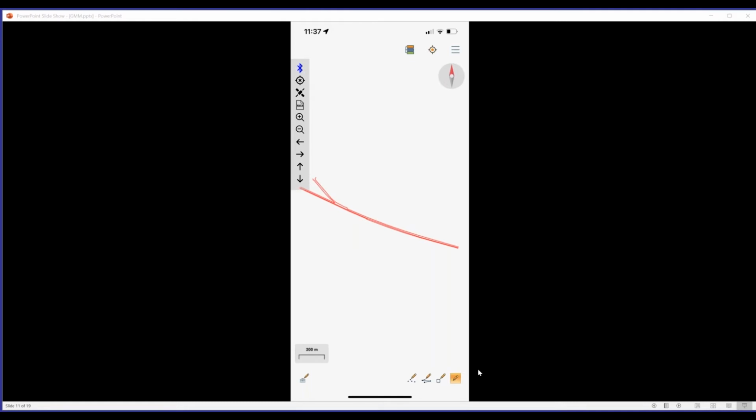I'll pause for a second here. We had a couple questions come in. I'll try to answer at least one here as we're moving along. Somebody asked if they could explain what kind of accuracy we would expect in Global Mapper Mobile. That is always going to depend on the external units that you're working with. If you're just using the phone's internal location services, cell phones usually get about plus or minus 5 meters, so not really great for high accuracy work.